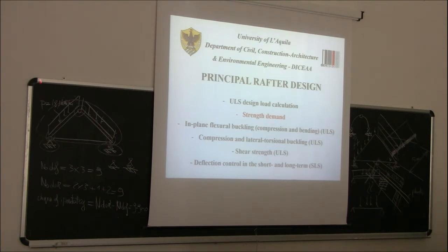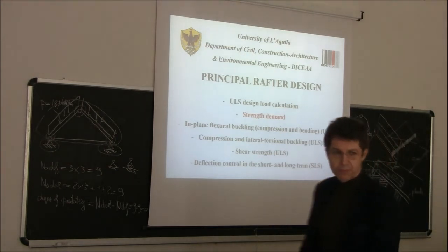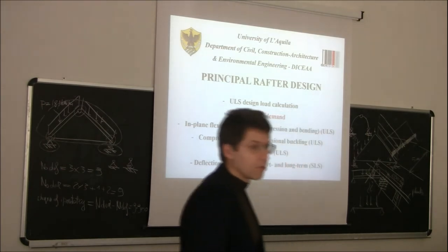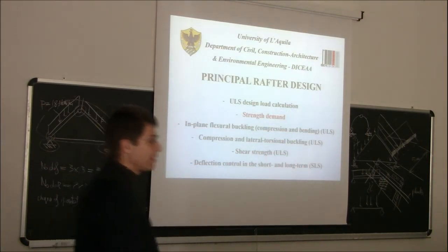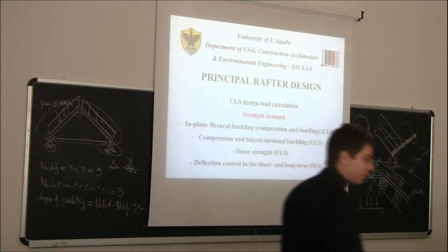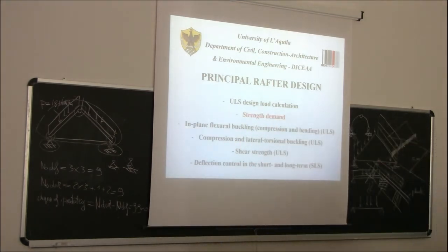In this case, since we have a UDL, what can we expect in the beams? Bending moment. We can expect also bending moment and shear. Okay? So in this sense, this is a non-typical truss system. So how can we solve this system now?